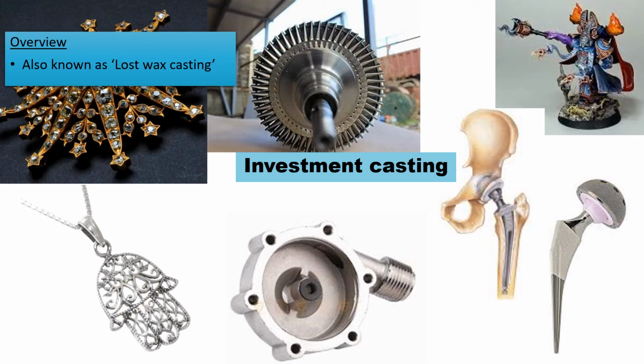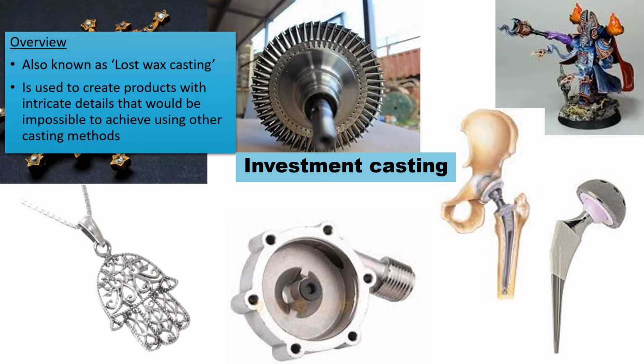So investment casting is also known as lost wax casting. This is because the pattern that is used for this casting process is made out of wax, and it is eventually melted away. It is used to create products with intricate details that would be impossible to achieve using other casting methods. So if you need a very, very beautiful, exact replica of something, you would use investment casting to create that product.